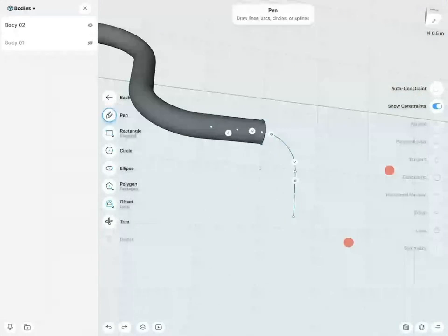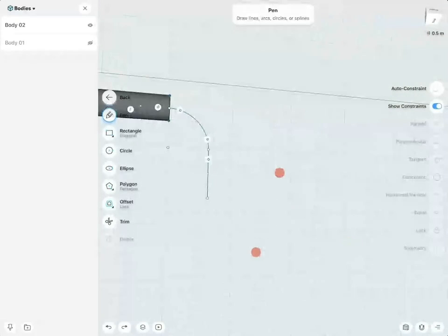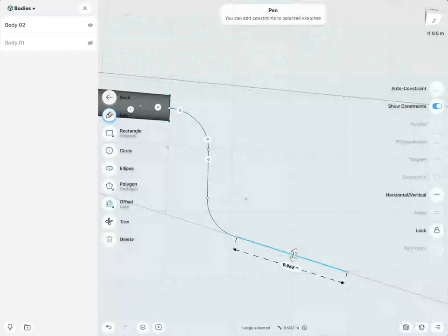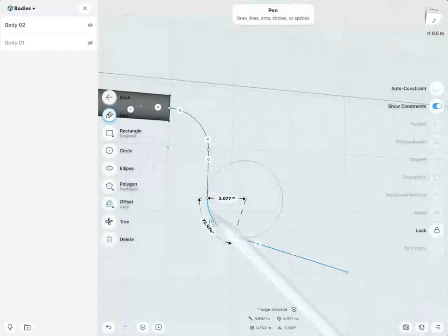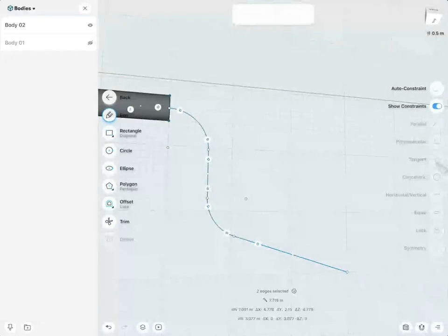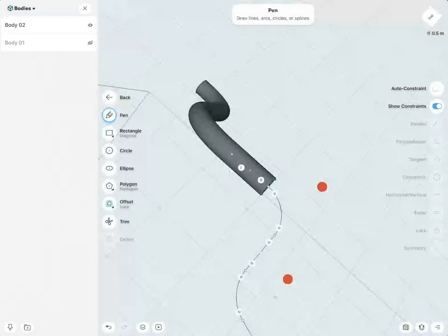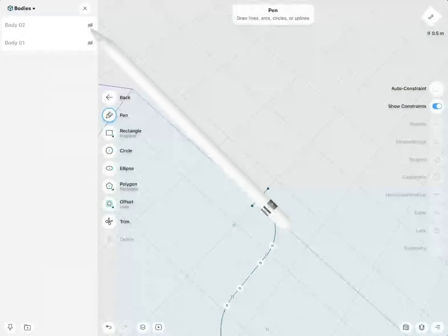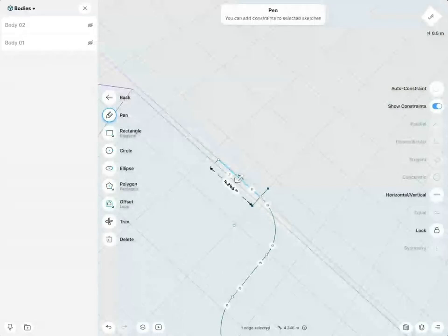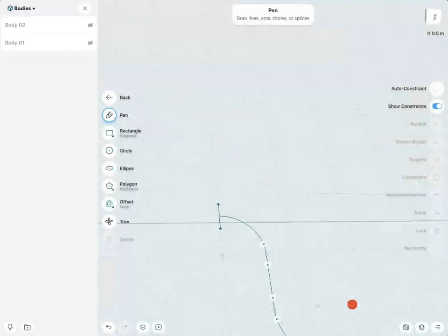Very good. Now if we want to continue this game, we can just draw another element, another arc out. Maybe here, this one now we do at an angle there, and then this line onto here, be tangent, this to there, be tangent. Very good. I will hide this. This line we don't need anymore, so I will remove it.